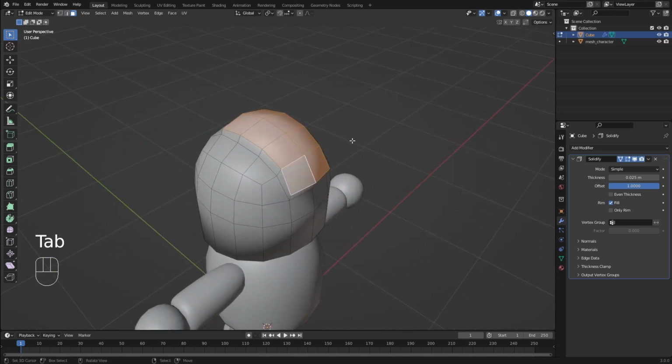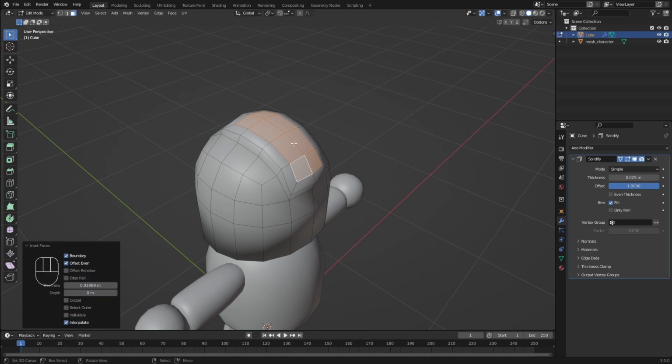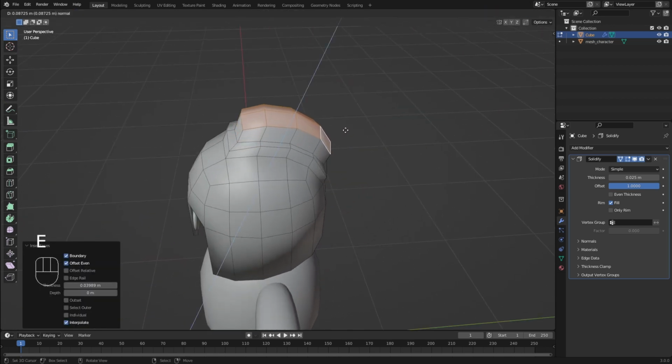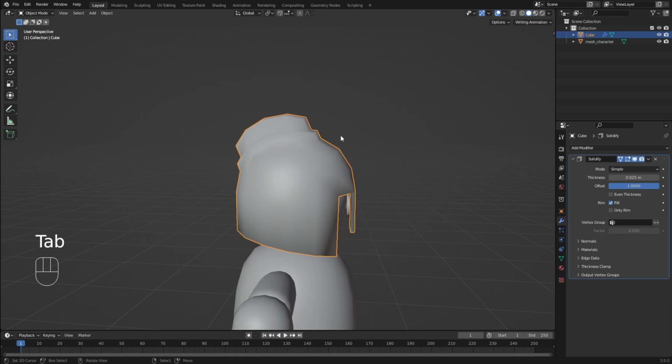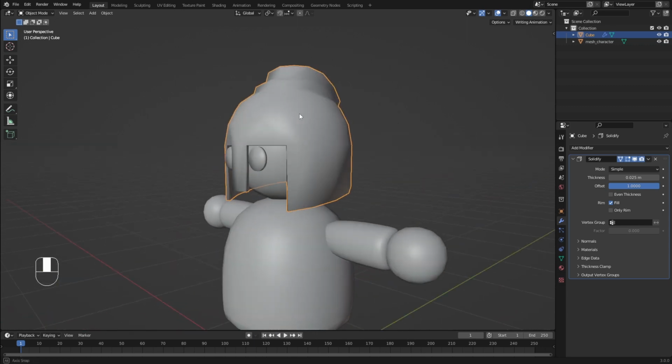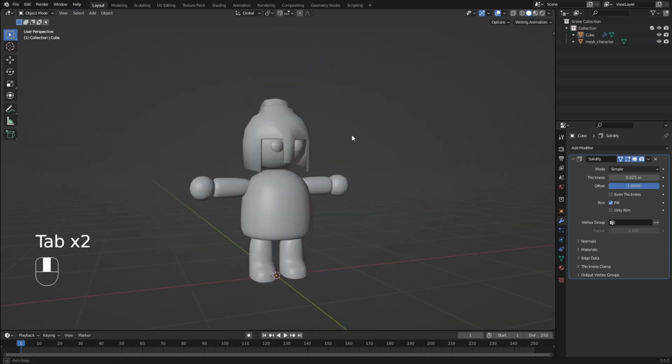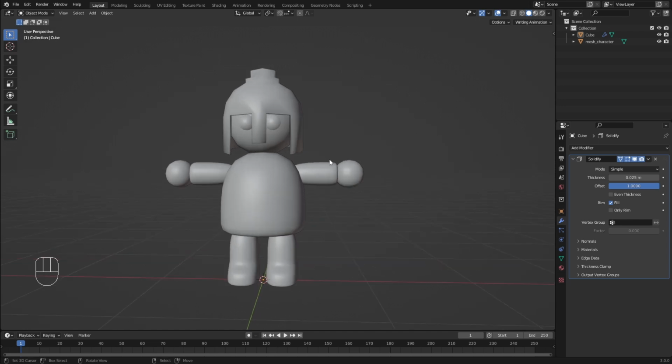And to extrude it even more, I'm gonna press I to inset, just like this. You can see, inset it, left click, and we're gonna press extrude again. And later on we can color these different colors and it will look quite nice. So that's our helmet done. What I wanted to have is also some kind of gear right here on the arms.